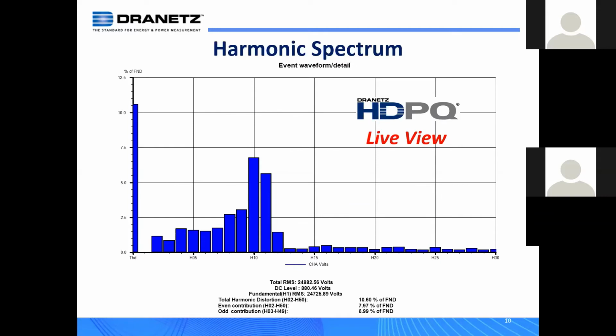So the bottom line with harmonics is that the utilities and even our alternative energy sources produce very pure sine waves, almost completely pure sine waves. So the generator throws those sine waves at usually a high voltage down on the line. When we receive it, we plug in stuff and we corrupt that. So the things that we plug into our power system create the very harmonic problem that we're looking at. So harmonics just need to be managed at the facility and also at the utility level.